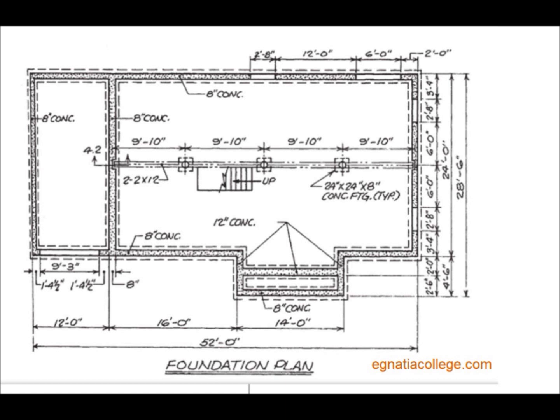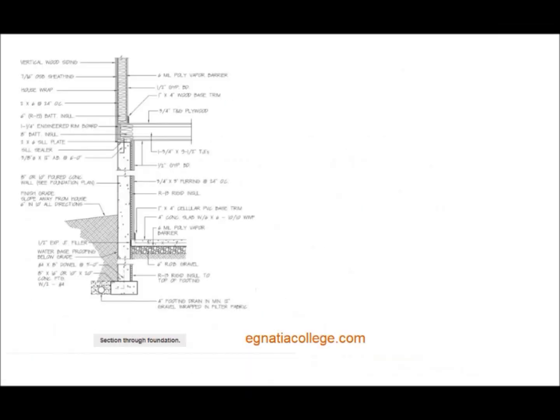The foundation plan includes overall dimensions, dimensions to interior corners and special constructions, and dimensions of special smaller features. It is customary to place the smallest dimensions closest to the drawing. The overall dimensions are placed around the outside of the drawing. All drawing sets include, at least, a wall section showing how the foundation is built, how it is secured to the footings, and any special construction at the top of the foundation wall.